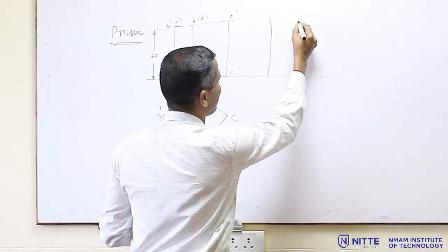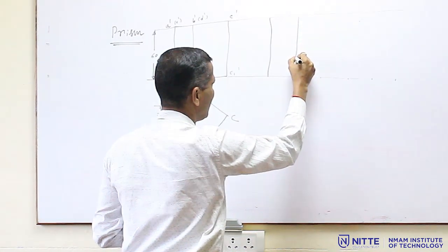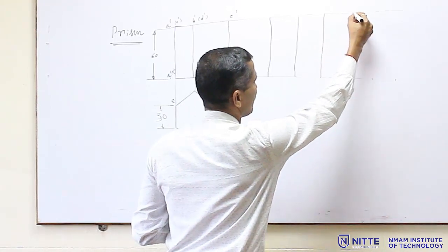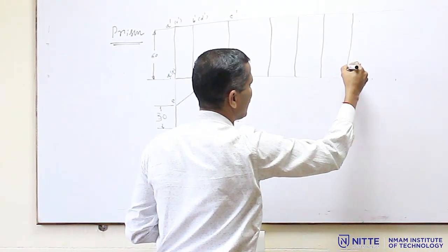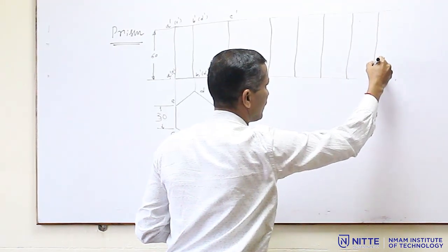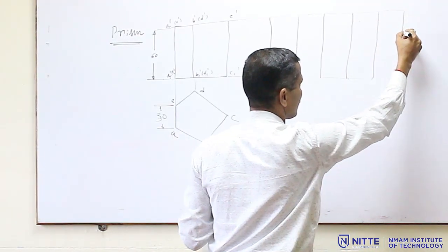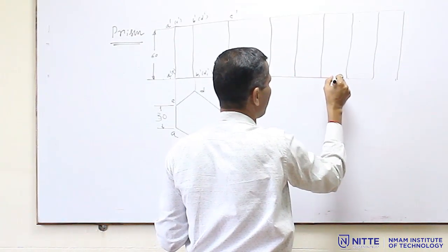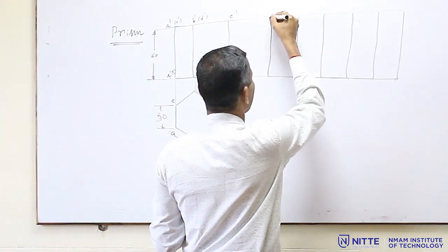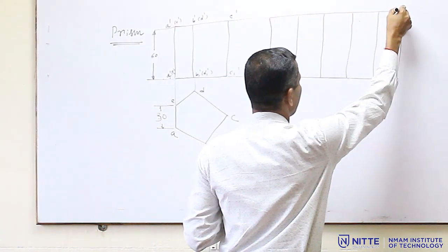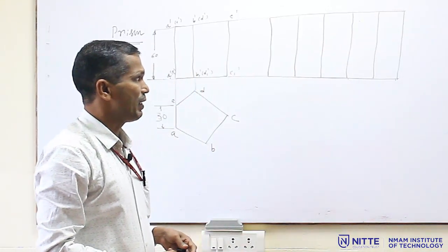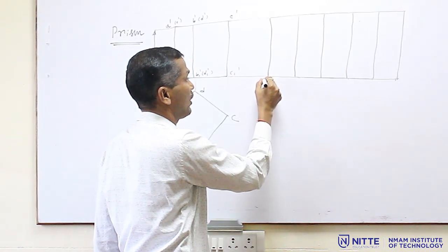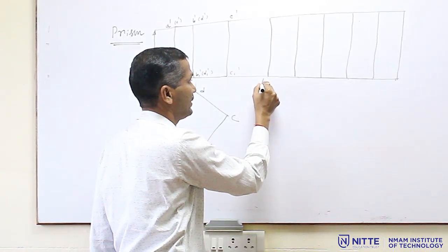Then afterwards, from all these points, you have to drop the verticals. Like this. Then dark this base and top. So, this is the development of a pentagonal prism. Normally, naming of the development will be done with the capital letters. All these edges you have to name.